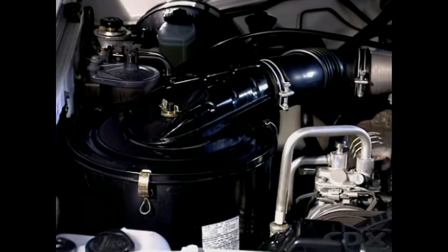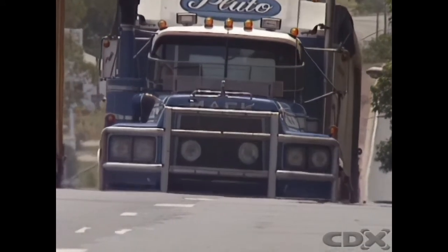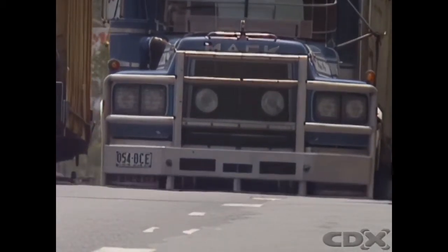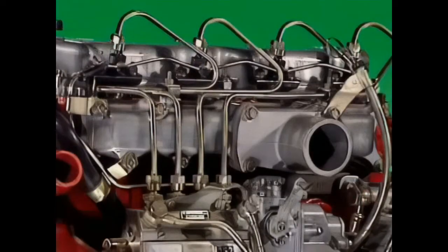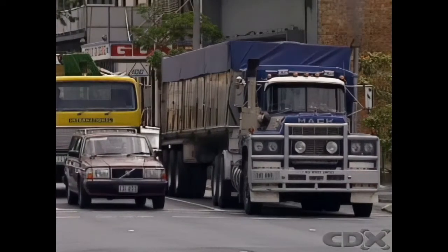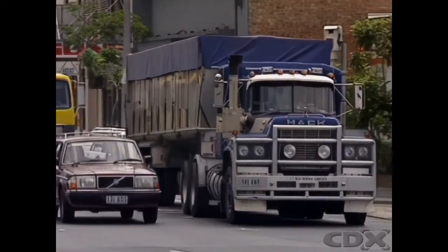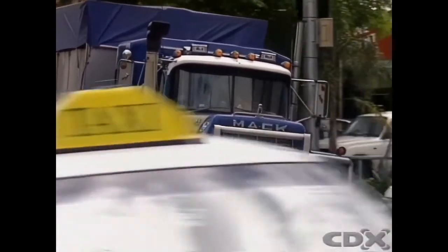The intake system of the diesel engine can be used to increase engine output. This can be done by increasing volumetric efficiency, that is, by increasing the amount of air that enters the cylinders. Output can also be improved by using large, free-flowing intake manifolds and by increasing the number or the size of inlet valves per cylinder to admit more charge into the combustion chamber. Another method is to use forced induction or supercharging to pressurize the intake of the air and force more air into the cylinders.